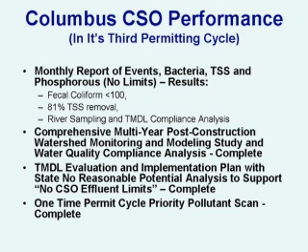This is the medium pressure UV disinfection system. It is treating or disinfecting the flow after the filtration, and the compressed media filters were knocking down the solids. We're getting 70% removal after an initial 35% removal in the vortex separators. So we're up at about 80+% removal, and the UV disinfection was found to be able to disinfect those flows quite well.